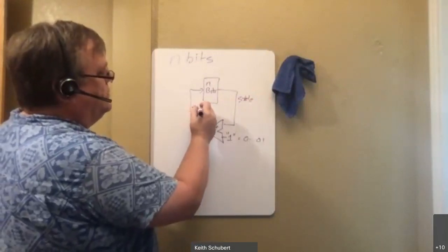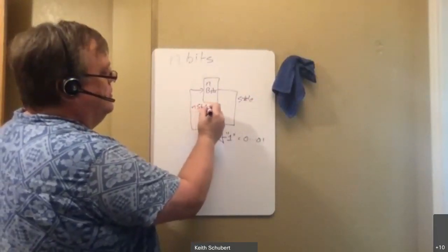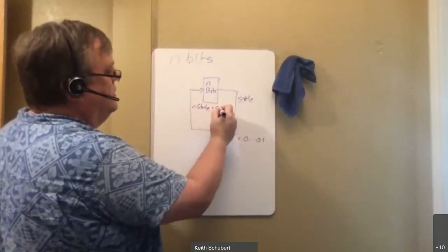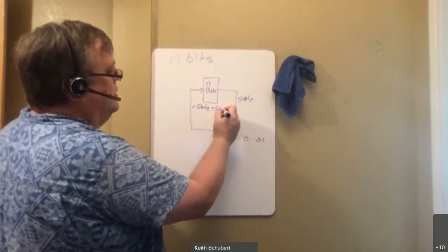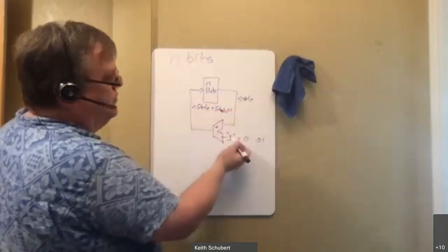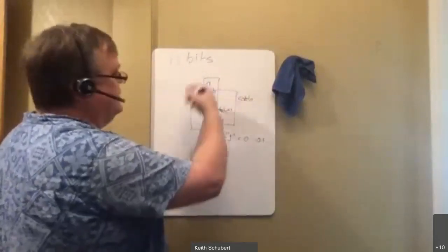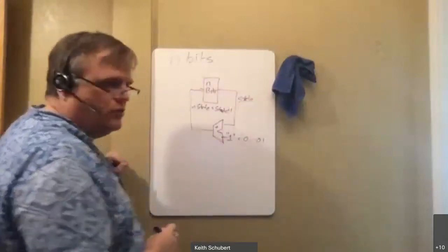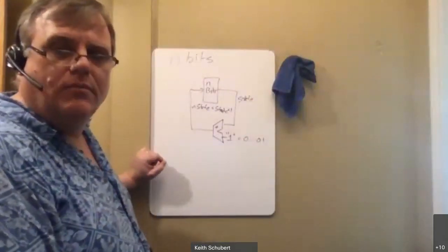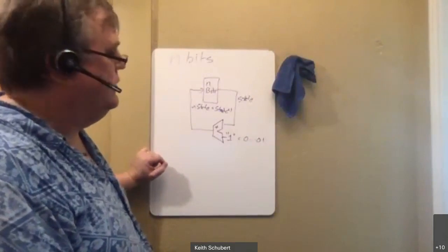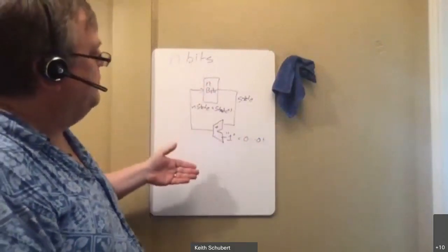So my next state is state plus 1 because of this. And I just read it in. So this will technically just keep counting up every time there's a clock pulse. So it's a very easy way to build this type of a counter.